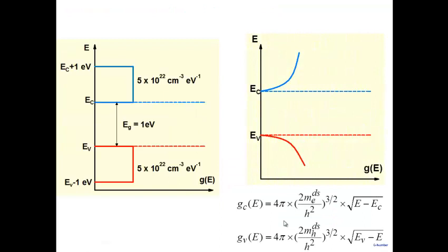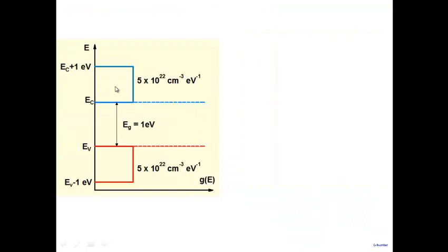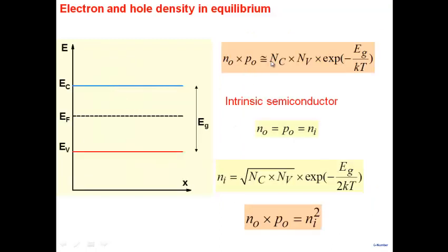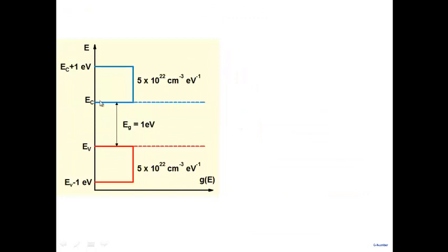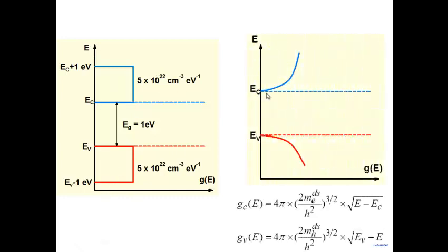All right. Now, as I said, all these relationships that you see here, N0 is NC and all that, I derived for a density of states which is given here. I assumed a simplified density of states. And I mentioned that for silicon, a more accurate density of states would be like this, where the conduction band density of states goes as GC goes as square root of E minus EC. Valence band density of states goes as square root of EV minus E.